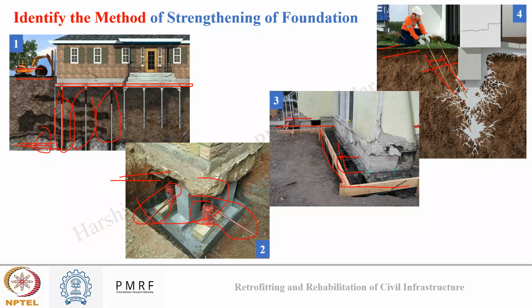So what you can do, you can always calculate the soil bearing capacity. You know how much load is acting on the internal column. You know what my bearing capacity of the soil is, and from these chemical methods, you know how much they will consolidate the soil. So suppose they consolidate the soil by 15% more, you know how much my soil bearing capacity will increase, and whether that increase is sufficient to take the load or not.